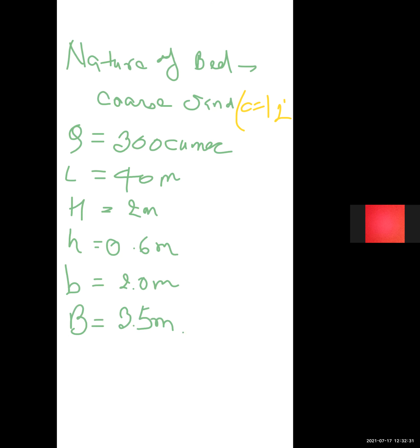1.5 meter. So the total maximum head loss can be calculated, that is HL equal to 2 plus 0.6, that is 2.6 meter. This is the total head loss.